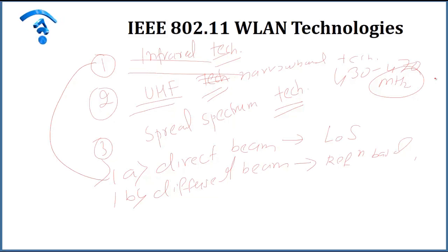If we summarize UHF in general, the advantages are the longest range, obviously, and a low cost solution for a longer distance site with a low or medium data throughput requirement. The disadvantages, I think there will be more: no multi-vendor interoperability, low throughput, interference potential, and obviously large radio and antenna will be required, so the wireless client size will be larger.